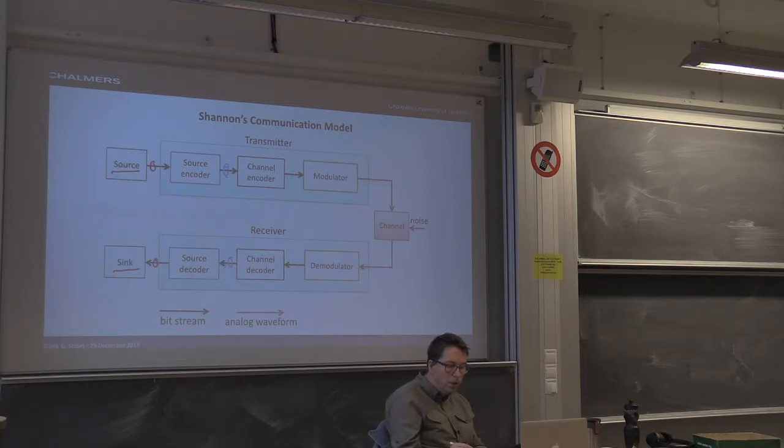The problem is that we are transmitting data over a physical channel, which is unpredictable. It contains noise, interference, and so forth. So transmission over the physical channel can never be error-free. There is a chance that we need to protect these bits before transmission. So we do data compression to get the essential bits, and then we protect the essential bits with the next block, called the channel encoder. And then we produce new bits here.